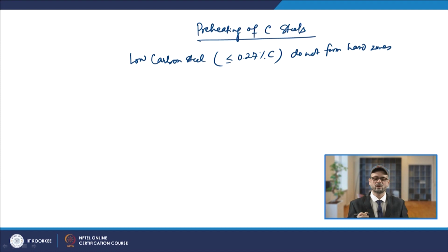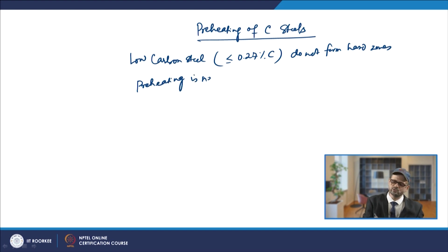So, with these low carbon steels, preheating is necessary only when welding exceptionally heavy sections.